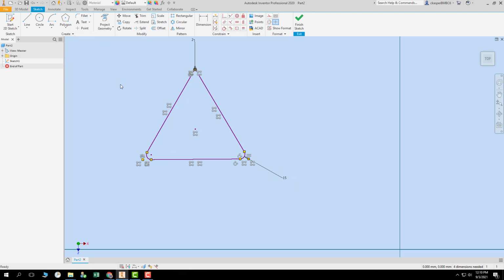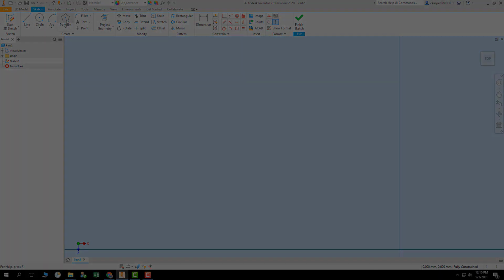And we can close that. That's a 2-dimensional fillet. It will also do 3-dimensional. It will fillet an entire side of a sharp angle of an extruded object. So that was fillet, and we'll cover those other ones later because they are actually used for different purposes. Okay, that'll take care of this video for the introduction to these line tools.